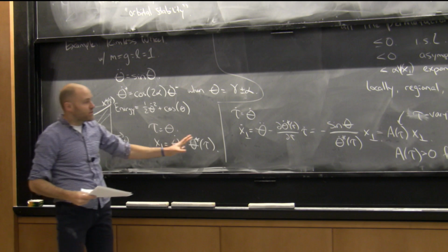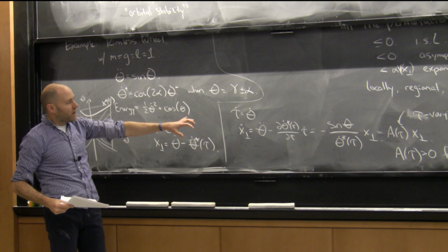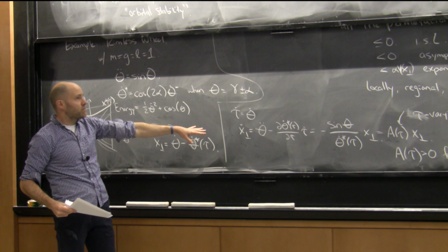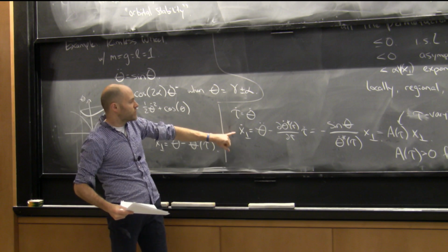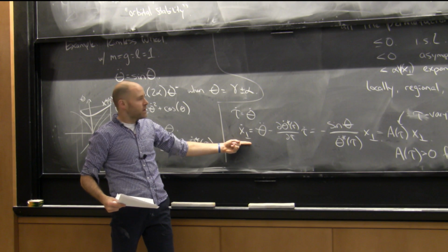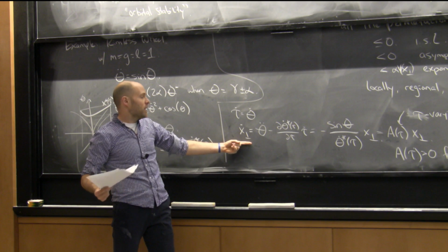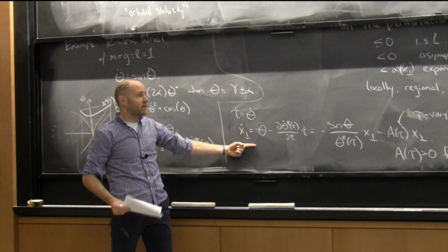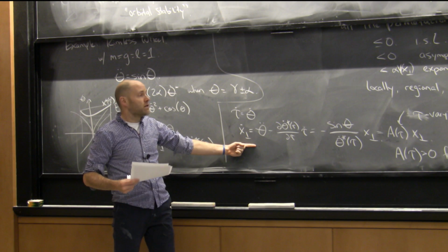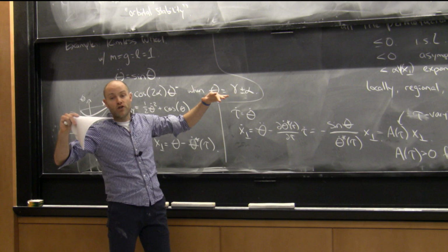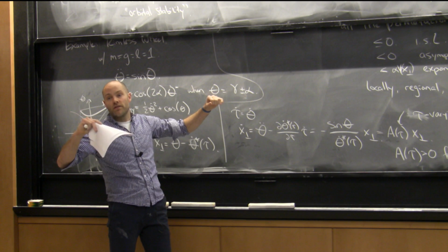Okay, now you can imagine for these conditions, for more complicated surfaces of section, I can still run some machinery to figure out what my new vector field looks like in the transverse coordinates. And you can imagine, and we have written sums of squares programs to compute that, for instance. So I come up with a Lyapunov candidate, and then I use sums of squares to scale that candidate to find the largest possible region of attraction that's satisfied by that candidate.